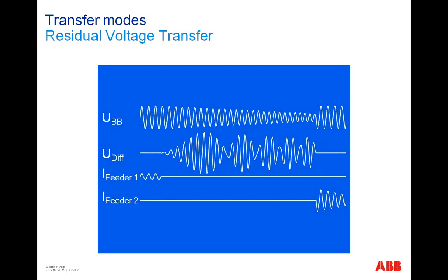If you have a good protection relay, a fast protection relay, means also protection relay state of the art today, then you will have always the chance to have the fast transfer mode. Normally you have always the fast transfer mode. And only if this is not possible, then normally the transfer will be performed at first phase coincidence. This is more or less like a backup.